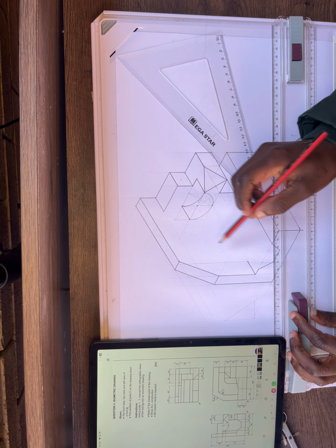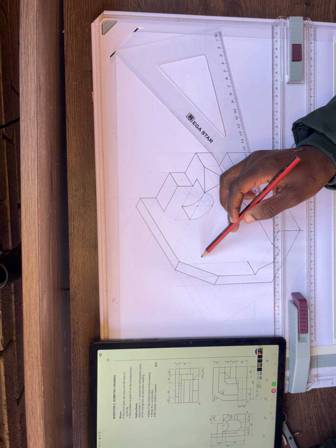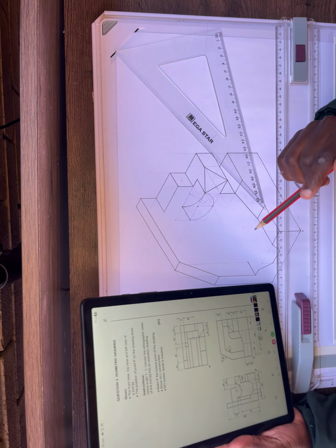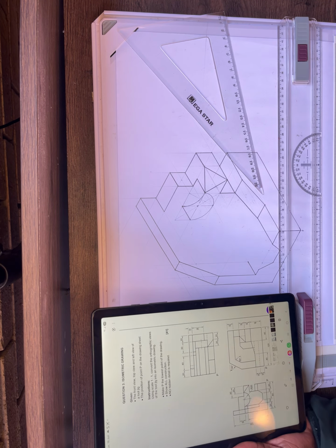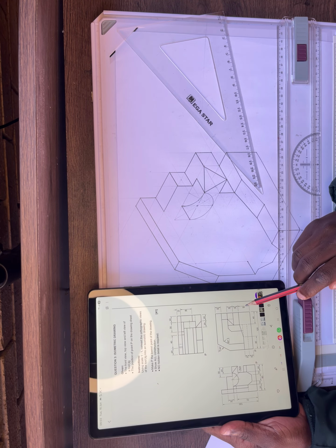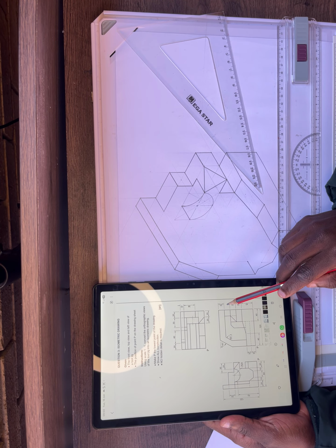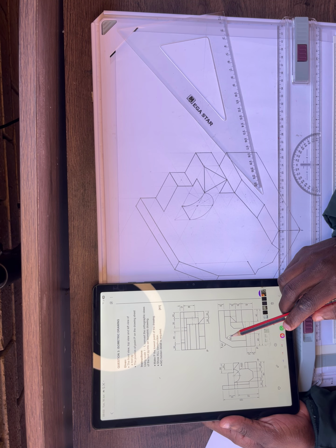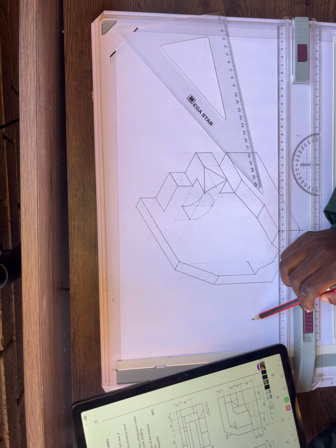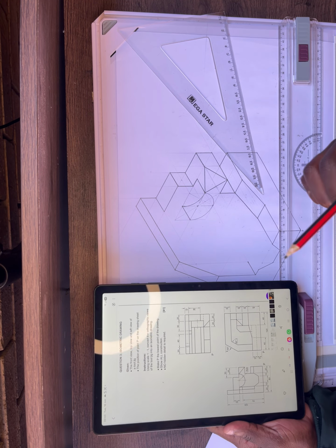Now you see that the very same corner that I did is this one, but now I have to find the dimension here. How am I going to find that dimension? We are going to apply the very same thing that we did this side. Find one side and then measure 60, the other one will construct itself. If you can check, we are having 40, 20, 20, 20, which means from here to here is 20, which tells us that one side of this 60 here is also 20. All right, so instead of measuring 40 at first, now we are going to measure 20 to be one side, and then measure 60, the other side will construct itself.